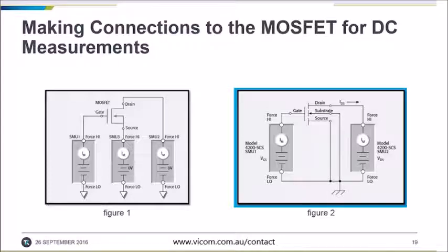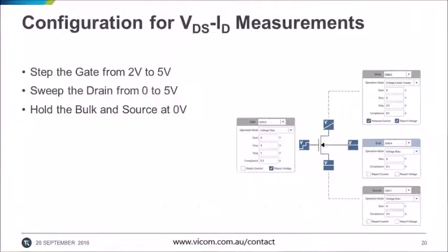Also, the current and voltage at the source terminal cannot be measured. This can result in errors in calculations later on. Everything that we went over earlier still applies here, however. It is important to keep cables short and make 4-wire connections as close to the DUT as possible. Also, guarding and shielding are still important.